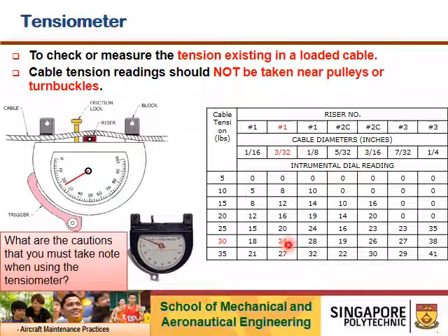But this is not the actual cable tension in the system. Although the dial displays 24, the chart will tell you that you need to convert. 24 means the actual cable tension is 30 pounds.